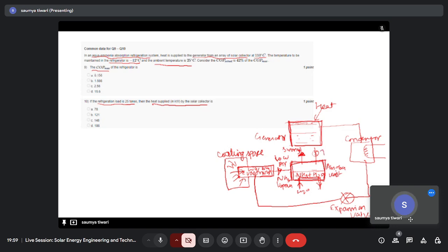This is the pressure valve, reducing pressure. So what happens is this strong ammonia water aqueous system now goes to the generator, where heat is utilized basically to desorb ammonia from this rich solution. Okay, so here is where your solar energy comes into the picture. So this gaseous ammonia is desorbed from the solution at high pressure to generate again this lean solution that can be sent back to this absorber.